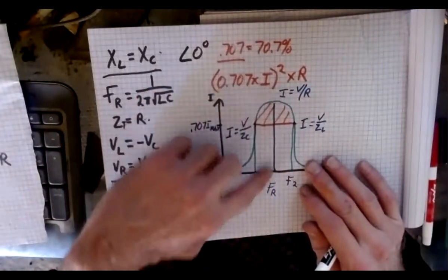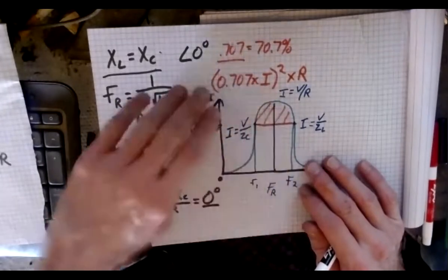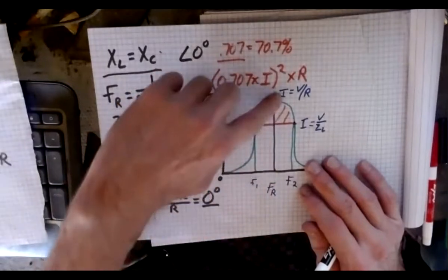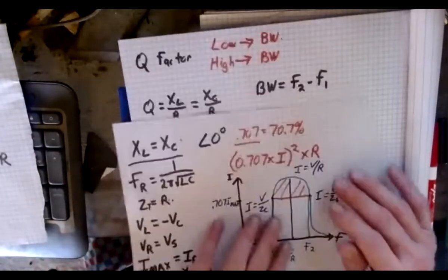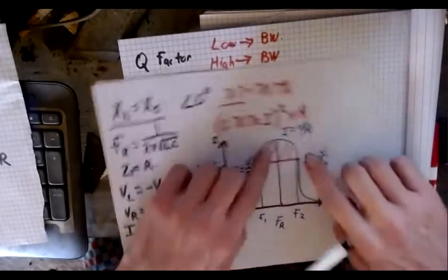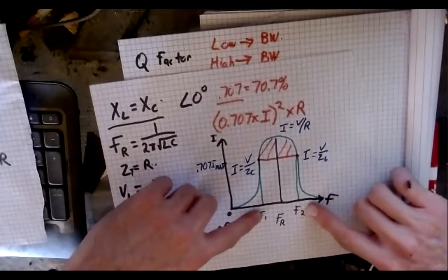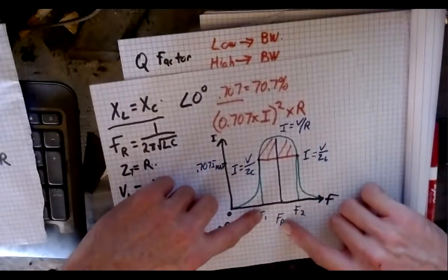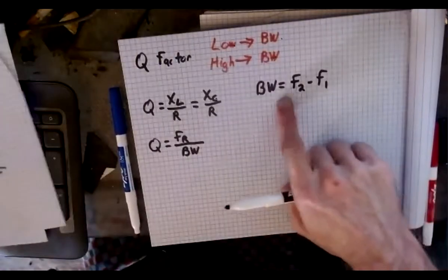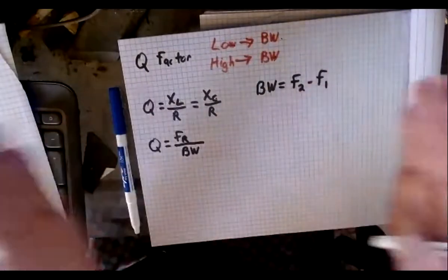Of course, we have to have our center and find out what my peak value is here, right? We look at our peak value and get that number, and then I have my center frequency, and then we do a fallout, and we have my lower end frequency and my upper end frequency from my center. Then we can come up with my overall bandwidth, or what my range is, okay?